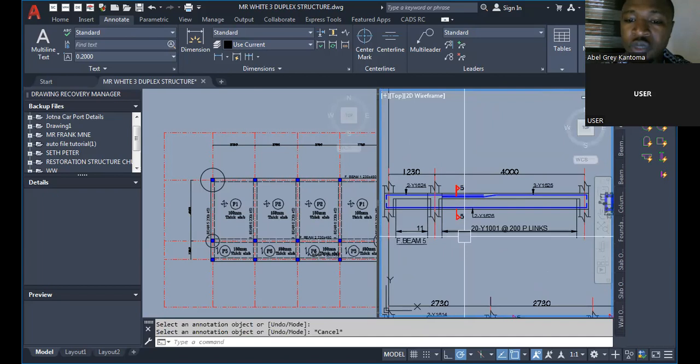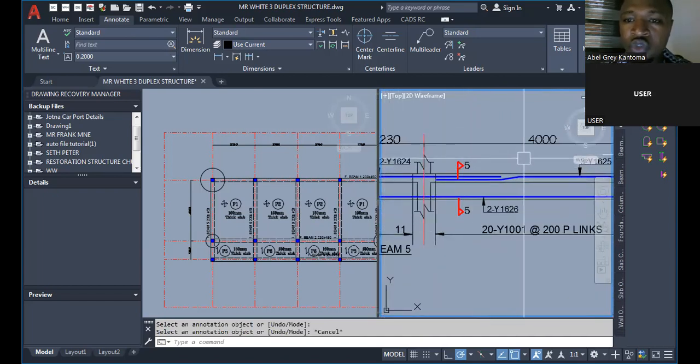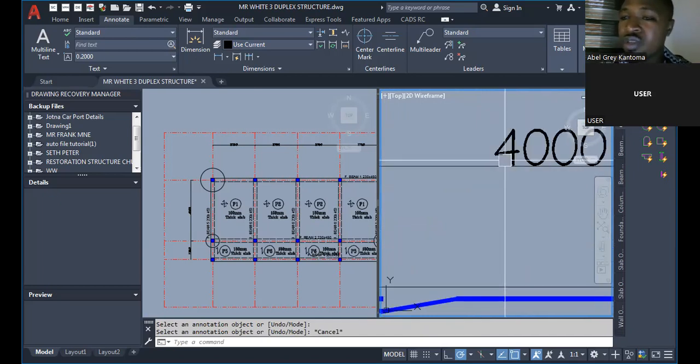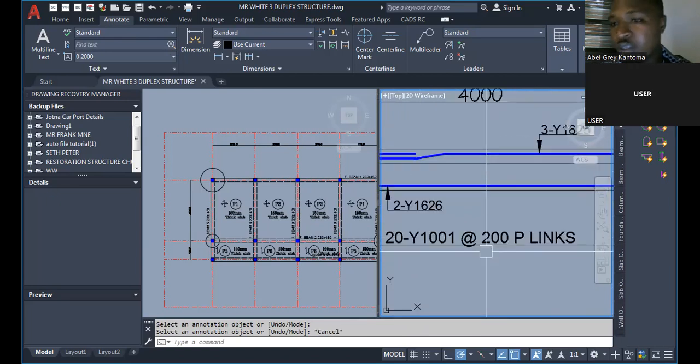And then how to get the links, I explained that to you: all you need to do is take the first two values that you see, divide it by 2, and it is going to give you that value, because our spacing is 200. But it changes. If you are using a spacing of 250, you cannot adopt the same thing I used just now. So depending on whatever your spacing is for your links, you just play around with it and you get the value right.